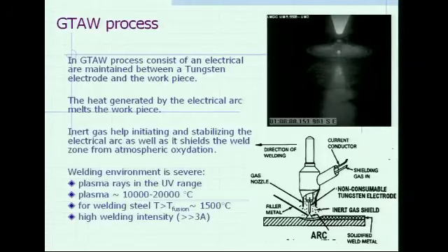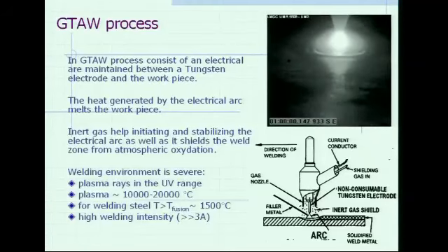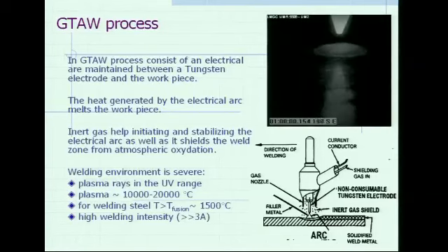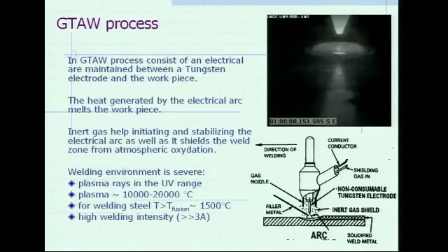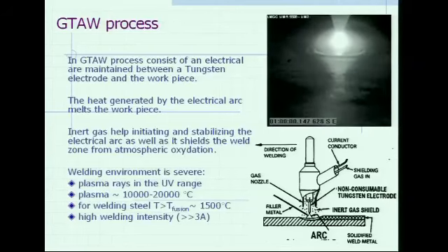So what is a welding process? Basically, it is a process that will assemble two metallic parts by melting a small part of the workpiece. You have two plates together, and you are welding along the border of the plates, and you melt this part. In arc welding, and especially gas tungsten arc welding, you use an electrical arc to melt the metallic workpiece.